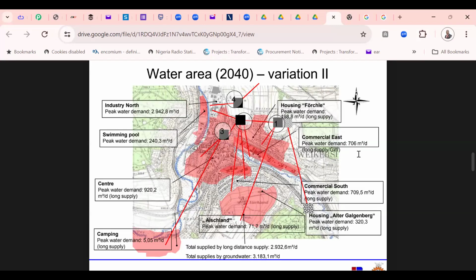In fact, if I see a place where the population equivalent is between 18,000 and 20,000, I will assume the worst case scenario of 20,000. Those of you that are structural engineers, you know what we do with beams. Once you do a beam of 4 meters and you see a beam of 5 meters, you can use the volume for 5 meters for 4 meters. True or false? True. If you have a slab of 5 meters by 4 meters, and you see a slab of 4 meters by 4 meters, you'll be wasting your time redesigning that slab. Just use the parameters for 5 meters by 4 meters.